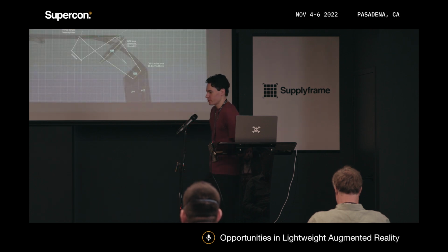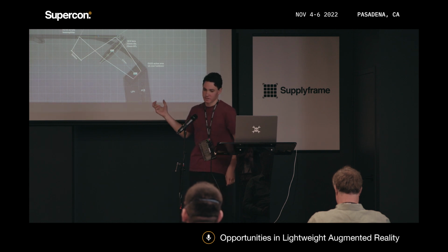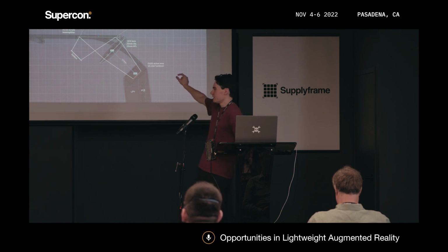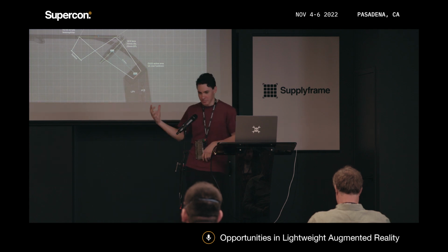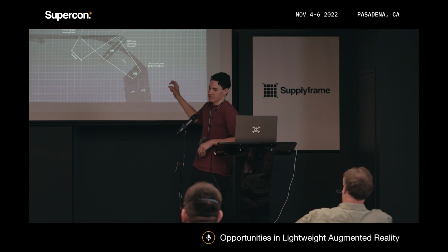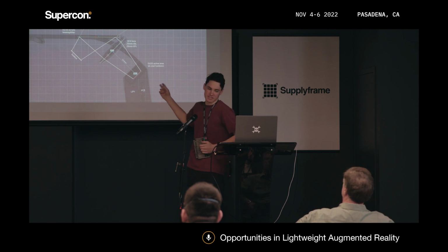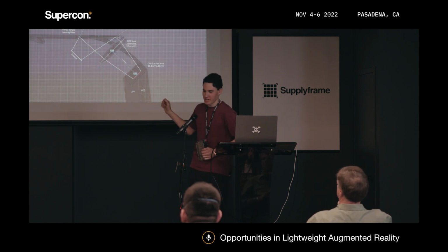Here, before I show the complete assembly, is an overview of a very simple optical setup that I decided to try. Of course you need to get the image from the OLED display to the user's eye, and about the simplest thing you can do is use a converging lens, in this case a double convex lens, and a beam splitter.